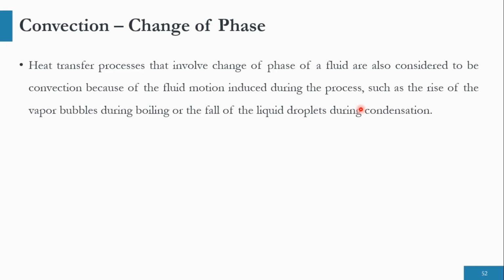In the condensation process, the opposite happens. The vapor is condensed to liquid. So accordingly, again, there is some heat transfer. In boiling, there will be a hot media or hot utility, while in condensation, there will be a cold utility or cooling media. So accordingly, with the heat transfer, we will say that this is a convection process which is happening over here in these two processes.